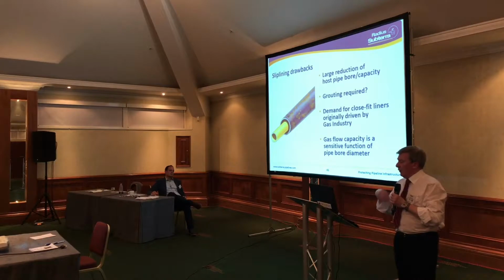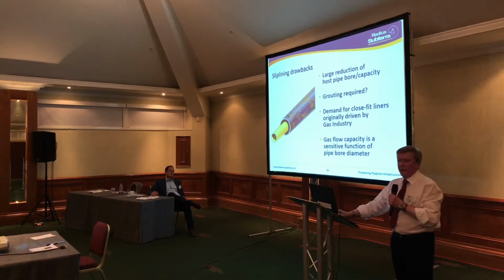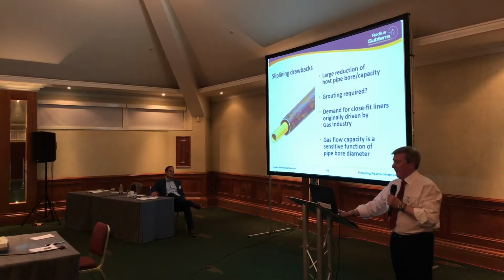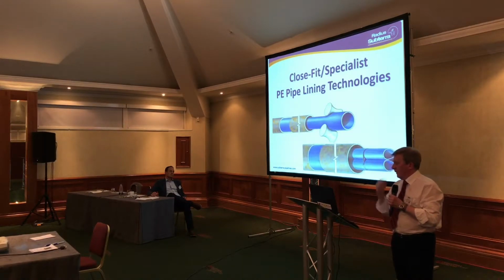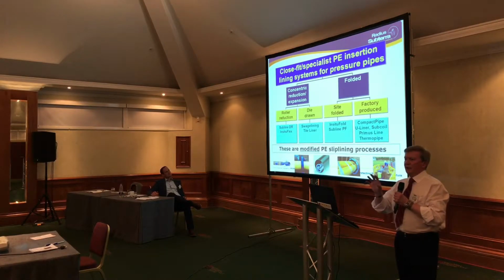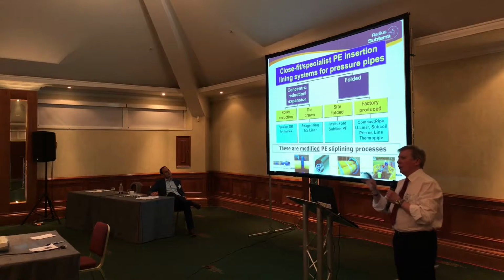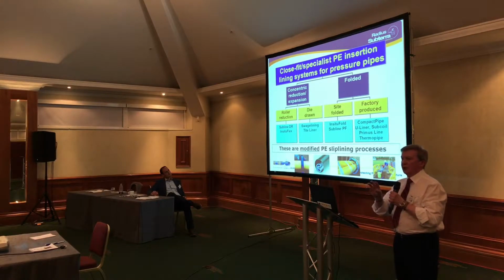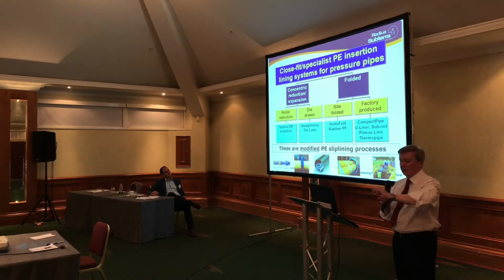That led to an interest in finding ways of maximising the capacity of PE-lined pipes, and spawned a whole raft of technologies for close-fit lining. Now, these can be broadly split into two categories. There's a concentric reduction type and the folded systems.